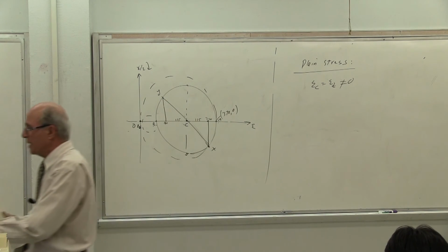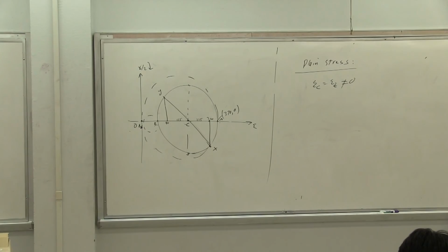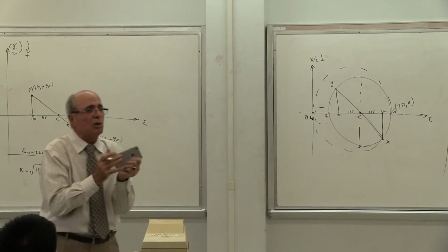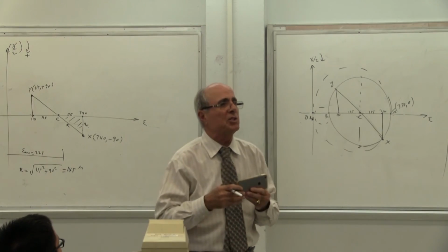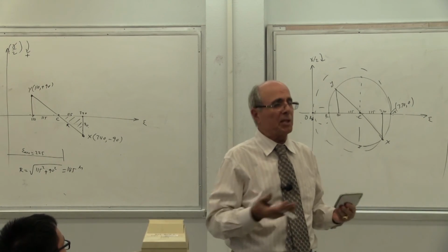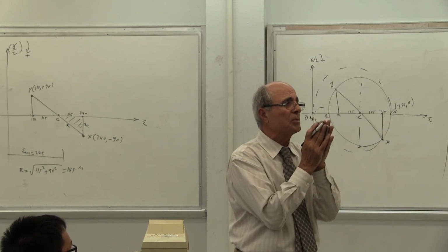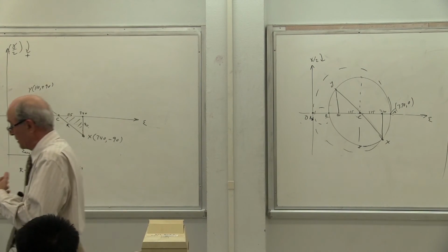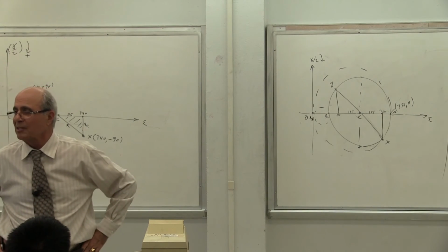It is obvious. Look at it this way, guys. If this is a plate, like my telephone, if I'm pushing it this way and pushing it this way, this side is going to get bigger. Or if I'm pulling it and pulling it, this side should get smaller. It's obvious, so it's plane stress because it's exposed. Is that correct? But if this is between two rigid plates, then it's plane strain, which is very rare. So plane strain is rare. Plane stress is the normal case. Is that correct or not?